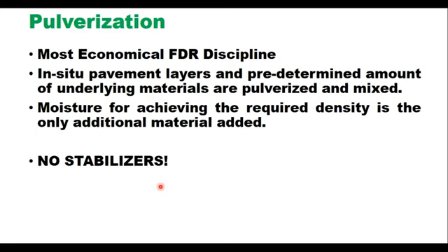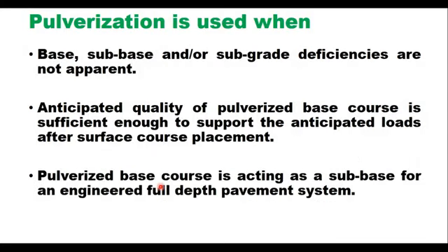This process is used when base, subbase and or subgrade deficiency are not apparent, and anticipated quality of pulverized base course is sufficient enough to support the anticipated loads after surface course placement. And this base course is acting as a sub-base for an engineered full depth pavement system.